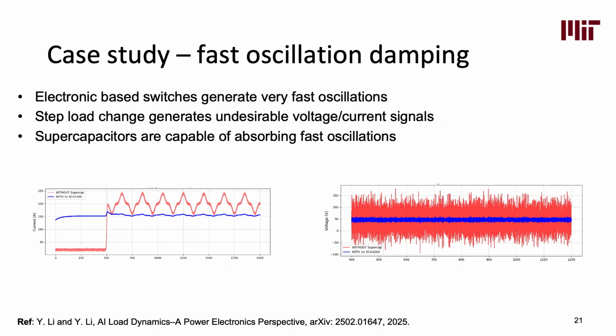And lastly, even on the faster time scale, at the sub-millisecond level, there will be more oscillations. There is a preliminary study from the University of Alberta, where they have a nice EMT power modeling on that. I built a model following their paper to see what happens if we have this additional supercapacitor, which is essentially already adopted by NVIDIA in their latest NVL72 and 144 systems. I think that's another very interesting study we can pursue.